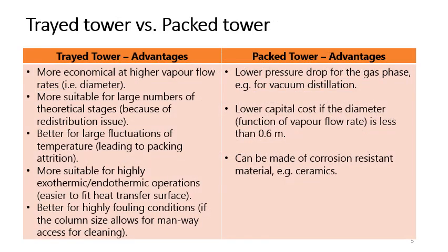When do you choose to use tray tower or packed tower? So you can have a look here. What are the advantages of tray tower and packed tower respectively? So basically, we use tray tower if you have a higher vapor flow rate, i.e. larger diameter, and if you have more number of theoretical stages, then better use tray tower because of redistribution issue.